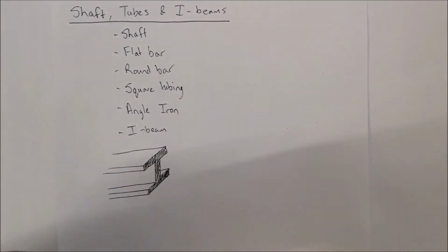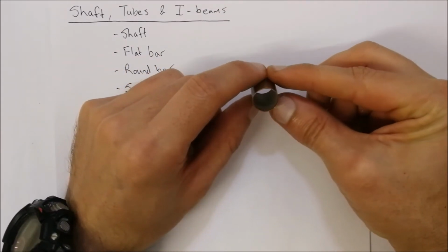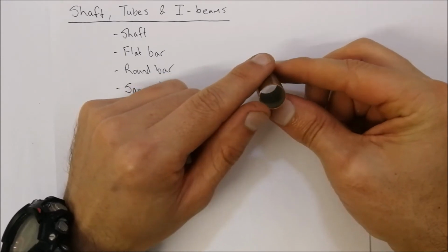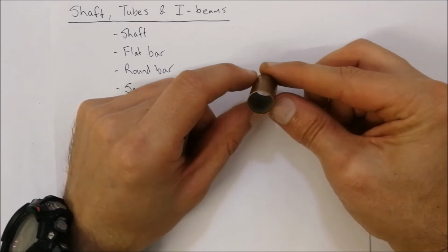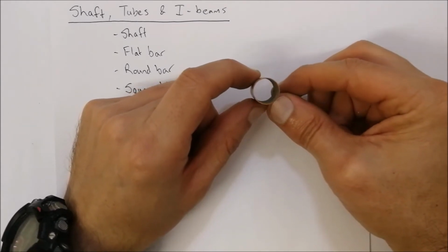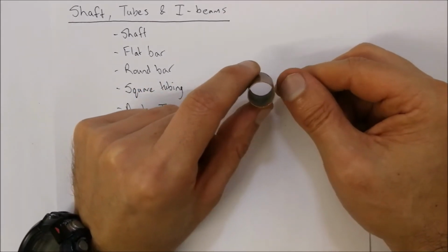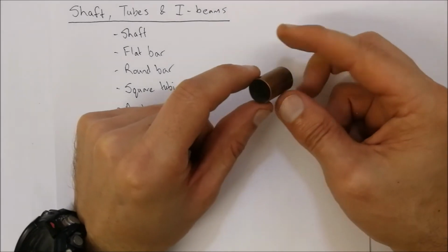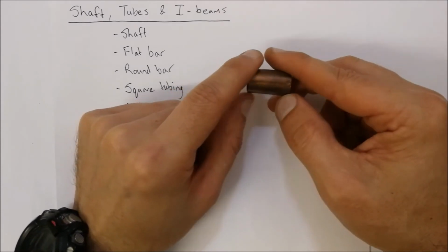And if you look at this specific copper pipe, which is essentially the same copper pipe we looked at previously, it is very thin walled. It's not a very thick walled copper pipe, and even with that little bit of wall that we've got there, it's pretty strong, and you're not able to bend it, at least not as easily as a copper rod. Okay, so keep that in mind with these round bars. It's less material that's being used, but again, if you want to try and bend it upwards, you're going to have the compression on the top and the tensile forces at the bottom.